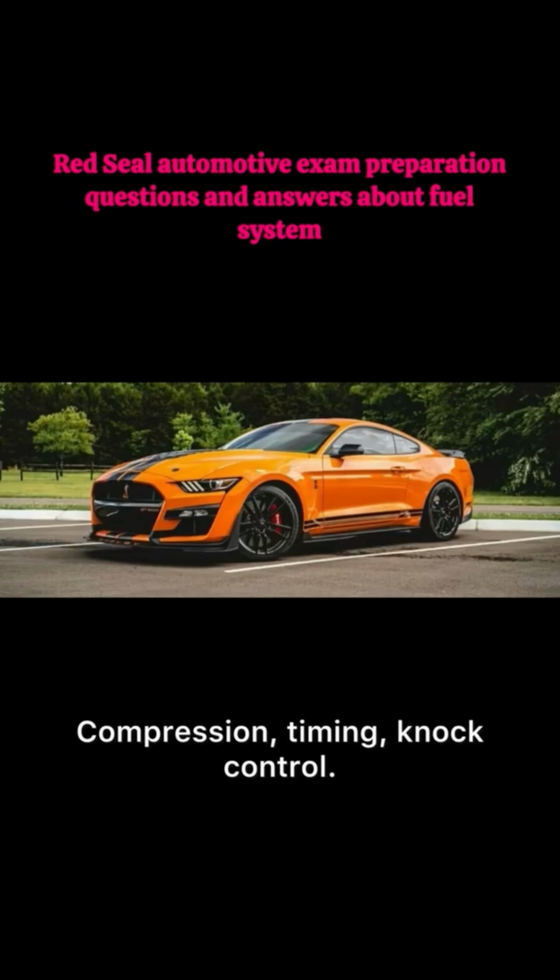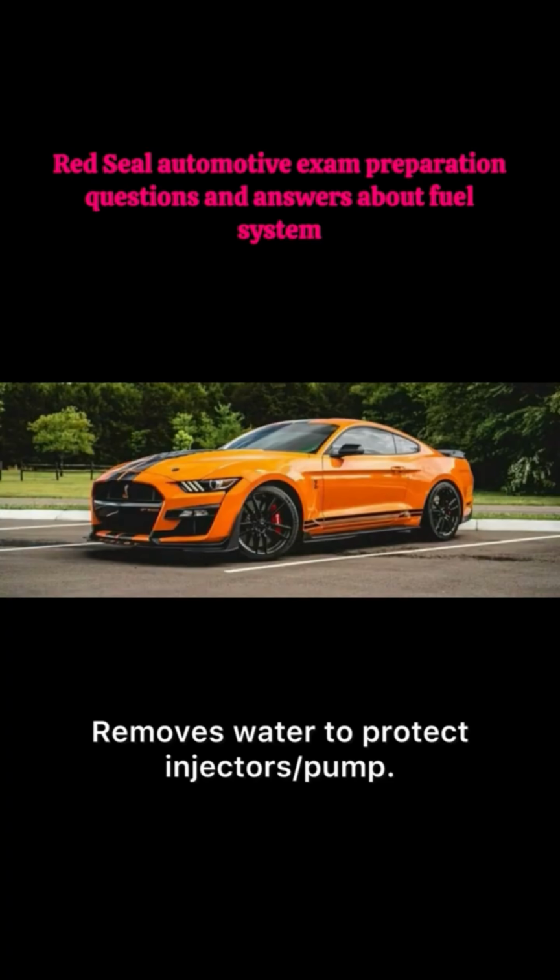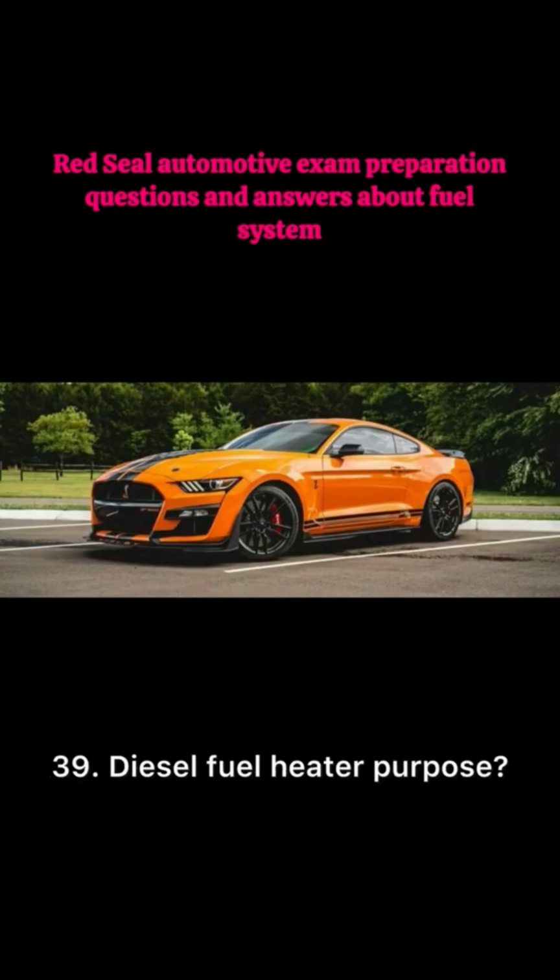36. What controls min octane needed? Compression, timing, knock control. 37. E10 fuel stoichiometric ratio. About 14.1:1. Needs more fuel. 38. Diesel water separator job. Removes water to protect injectors, pump. 39. Diesel fuel heater purpose. Stops fuel gelling in cold. 40. Common rail diesel pressure. 10,000 to 30,000 psi.